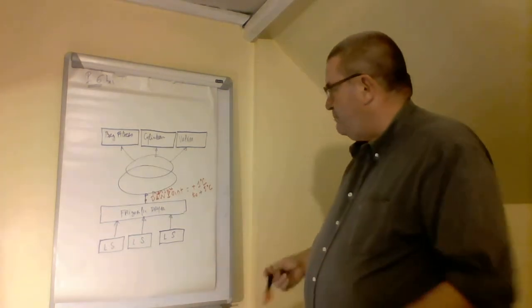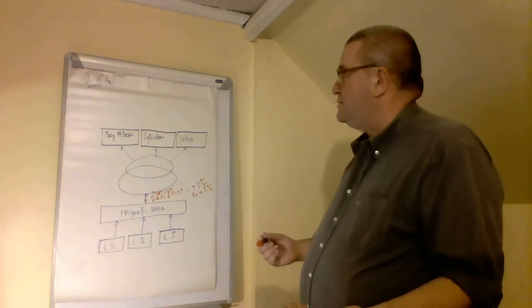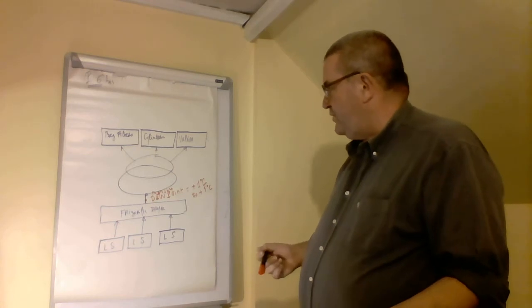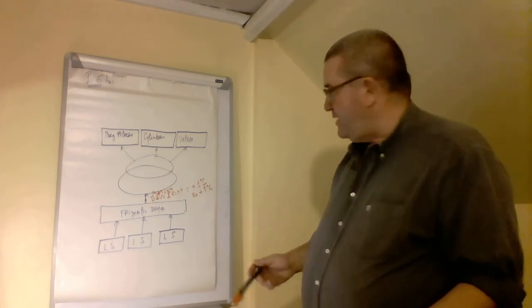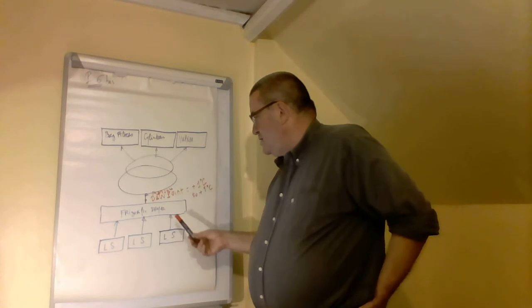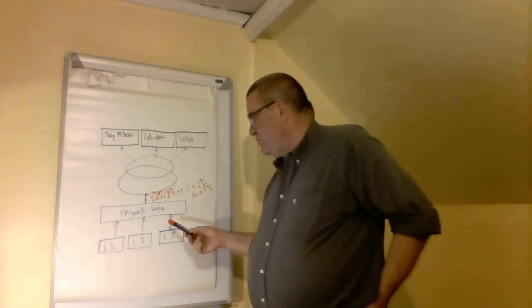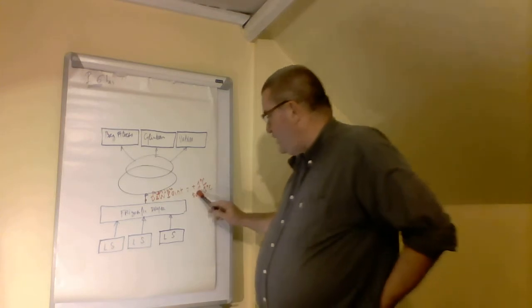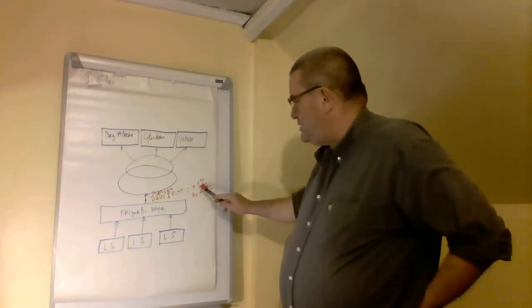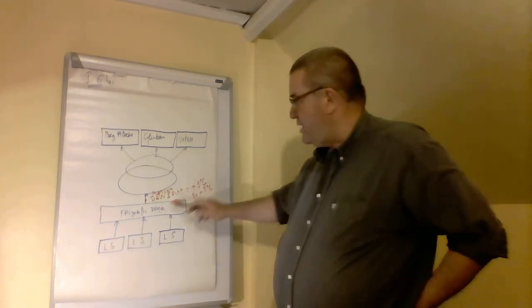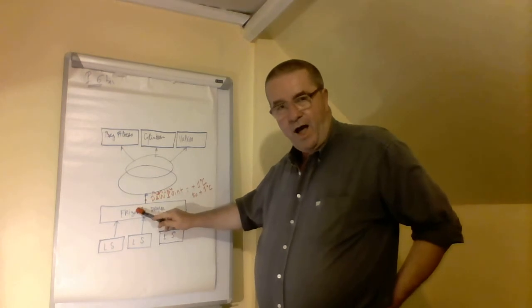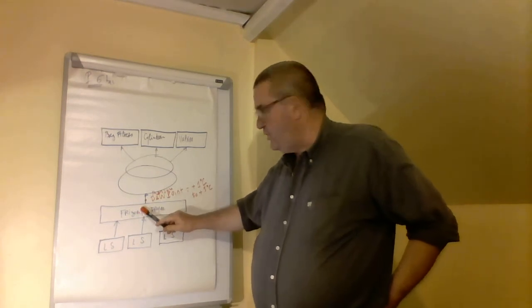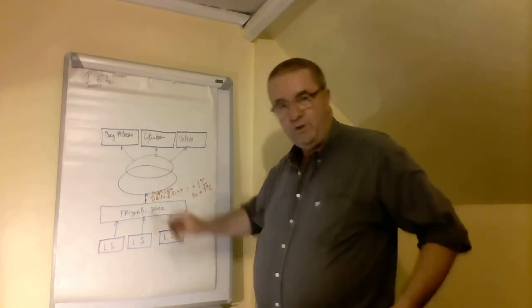What we shall see is that the biggest difference between the first diagram and this one is that we have chosen a dryer which removes some water, but not all the water, of course. And especially the dew point is superior to 0. Otherwise, you would get ice inside the frigorific dryer, and then no air would go through. It would make a tap.